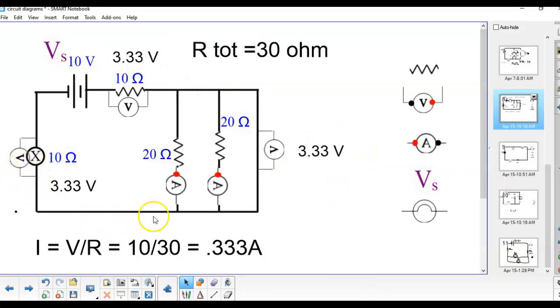Each of these is equivalent in resistance. And so they're each going to use up the same voltage. Now, notice they add up to 10. Yeah, 9.99 within rounding. Another way to do this is to say this is 1/3 of the total resistance in the circuit. And if you take the voltage divided by 3, because this is going to be 1/3, you get 3.33. Looks great.